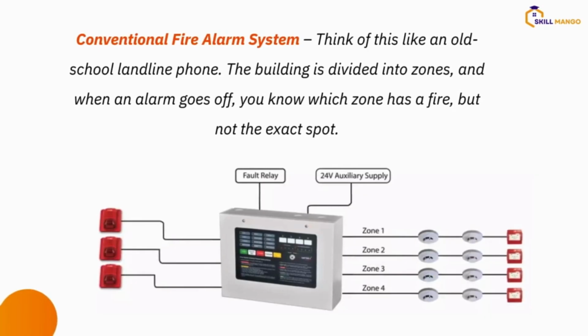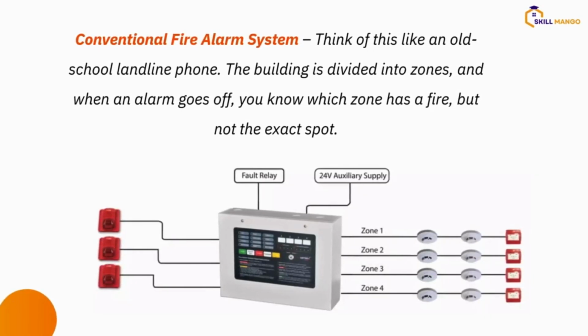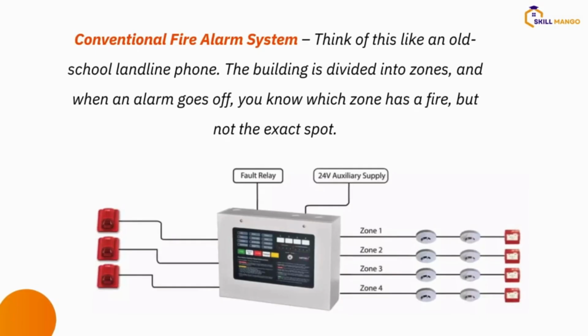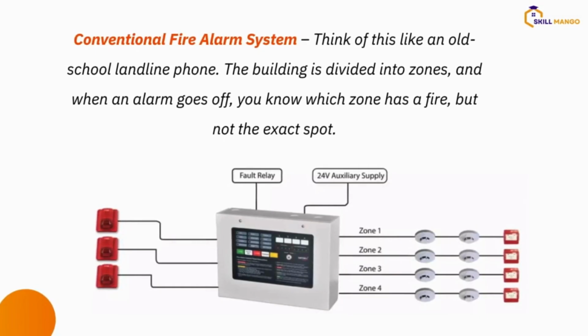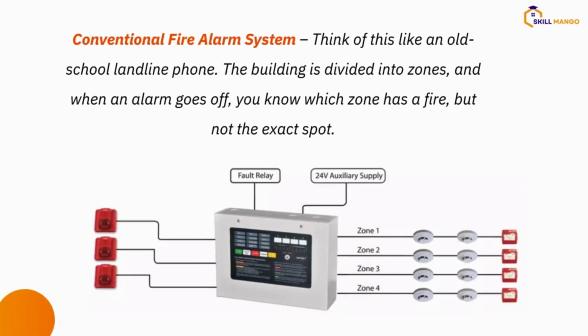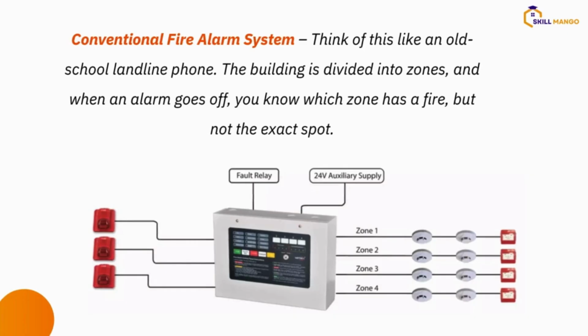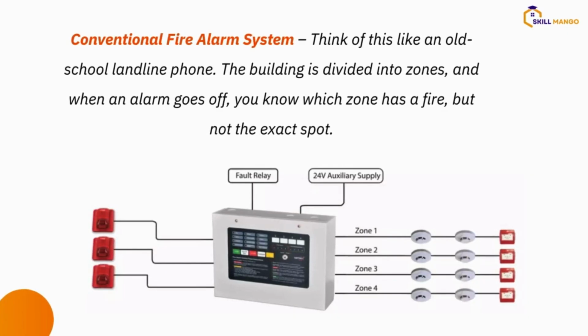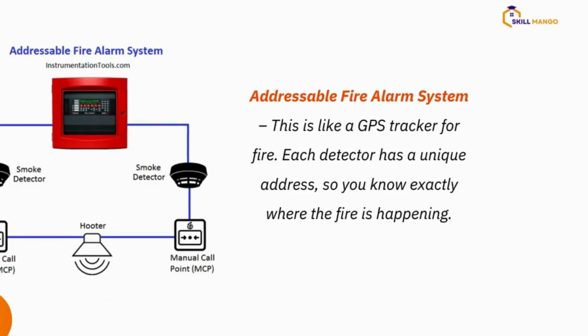And it's ideal you put your panel close to the exit point, maybe on the ground floor by the security post, so you can go and check it in case of fire. Because if you put it on the first floor or second floor, who wants to go there to check when there's a fire? Everybody's mind is to escape and run away. So it's ideal you put it on the ground floor in a very secure place and still be accessible and open for people to go and check. Okay, all right, that's that for conventional.